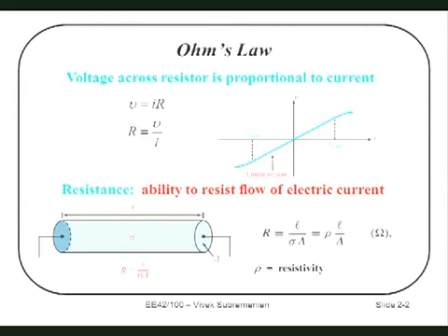The point is, the assumption, when I said going from this to double this was multiplying by 2, assumed that all the resistance in my measurement came from this box, and there's no resistance associated with the contacts. Because think about, let's pretend the contact contributes 0.1 ohms. Okay? Let's pretend. Then this would be 0.1, this is 0.1, what's left in the box? 0.8. What about here? I have 0.1, I have 0.1, I have 0.8 and 0.8. What should that give me? 1.8.